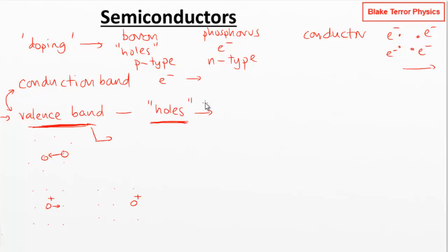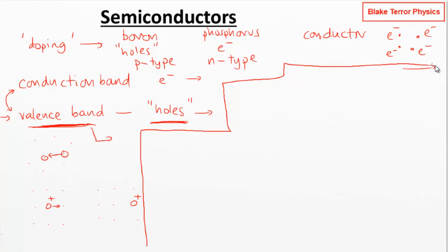And this is pretty much the foundation of all modern electronics, is based on the junctions between these different types of doped semiconductors. So before I get onto those, let's just do a quick recap of what I've said about semiconductors so far, because there's quite a lot going on. In terms of their conducting properties, they sit halfway between conductors and insulators, but they have that unusual property of, as they heat up, their resistance will drop, which is the opposite of what you get in conductors. And that's because of this movement of electrons between valence band and conduction band.